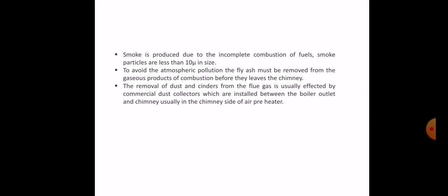The removal of dust and cinders from the flue gas is usually effected by commercial dust collectors, which are installed between the boiler outlet and the chimney, usually on the chimney side of the air preheater, to remove the fly ashes from the gases.